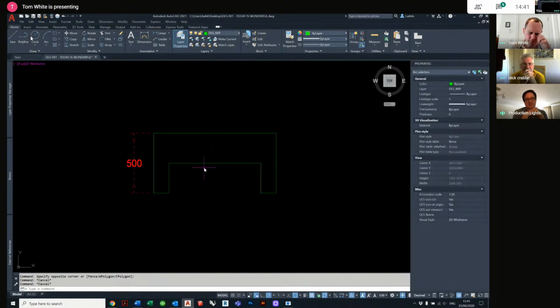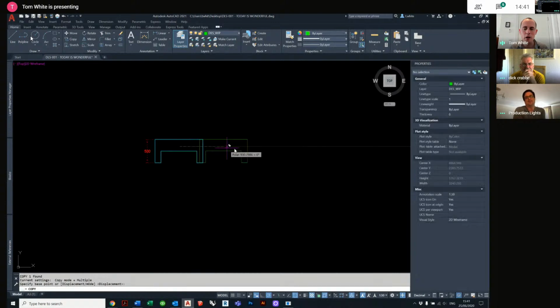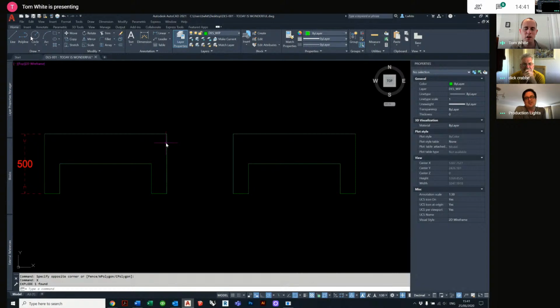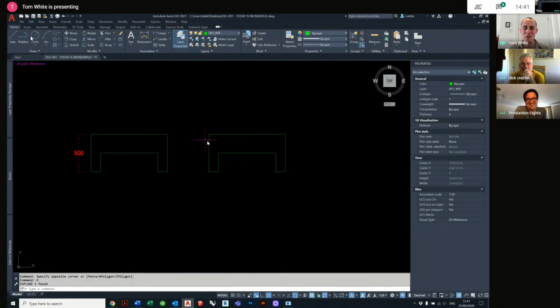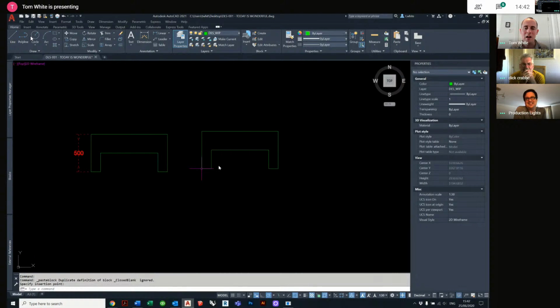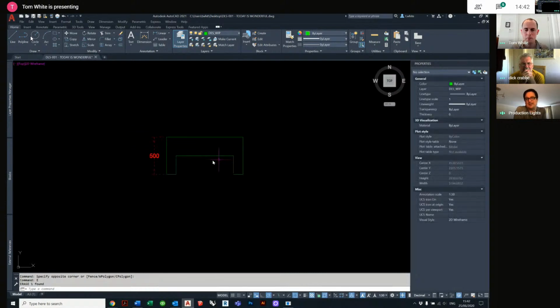Yeah, because CAD will give it some random letter-number combination if you don't name it, and it will mean absolutely nothing to anybody. Exactly. So a quick demonstration of this: I'm sorry, it doesn't look like a steel deck, but we all know it's a steel deck in this circumstance. So I have two steel decks, and I can do Control X and Control Shift V, and I now have a block which visually looks identical, and we know it's a steel deck, but it's called $C3, etc. And that doesn't mean anything to anyone. And you've got 100 of those in a list, you get very upset very quickly.